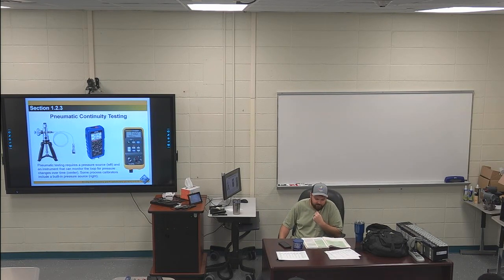Section 2, proving and calibrating a loop. Current loop trim is going to be important. I think we talked about that in the last chapter, but it's just adjustments that are made during the third stage. So that's a good one to know. Management system, sensor trim, zero and span calibration we talked about, that being the most basic calibration standard, but I use that one the most. In my experience, I've used zero and span way more than I use a 3 or 5 point calibration.